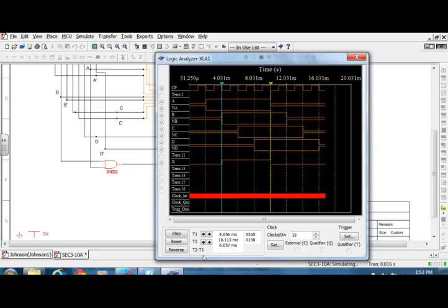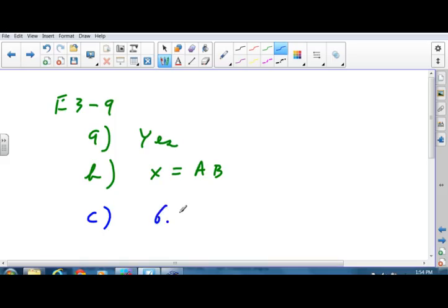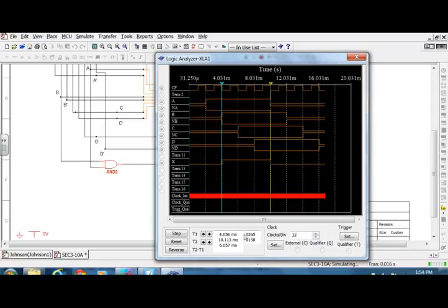And then I see that the difference between T1 and T2 is 6.057 milliseconds. What is the time width of the X waveform pulse? Ta-da! We're done. That's all there is, there ain't no more. But I can move my T1s and T2s around and find it.